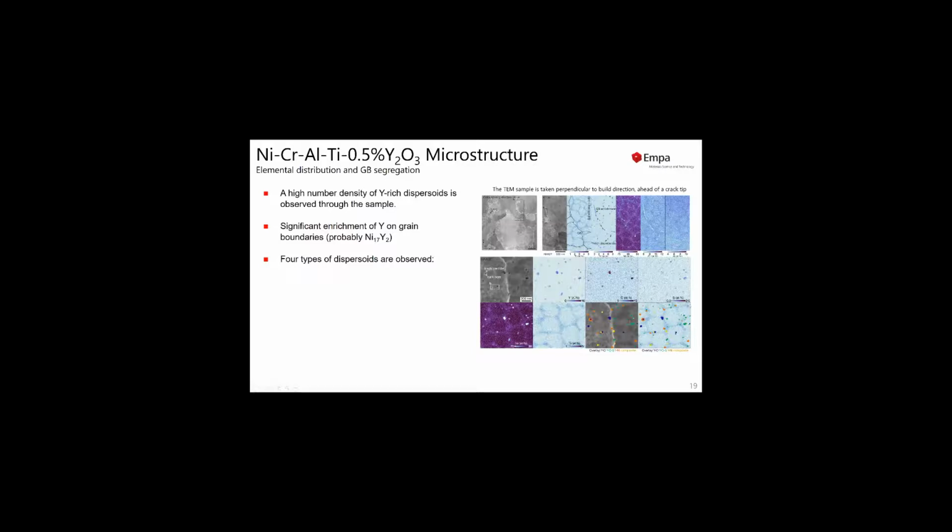We saw different types of dispersoids, basically four types. We found bright yttrium and nickel-rich dispersoids with a radius of around 16 nanometers. In addition to that, we found yttrium oxide-rich, but also yttrium oxygen sulfur-rich particles, which were significantly smaller. And we found some composite particles that were a bit more difficult to identify. These composite particles are an intermixed network of these yttrium nickel-rich and yttrium oxide-rich regions. Here, with some color coding, we've also tried to indicate the position of these oxides in our material.